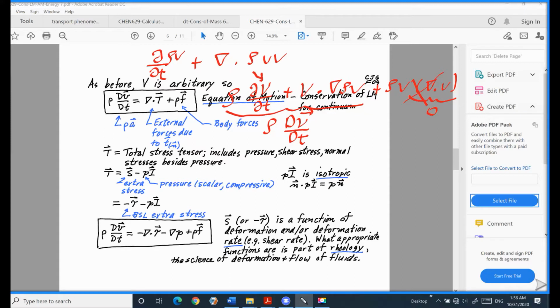On the right side, this term is the stress tensor, which includes the two forces because of the pressure and the viscous forces, and it comes from the body force, like because of gravity. We put the convective momentum transport inside this term by combining these operations.